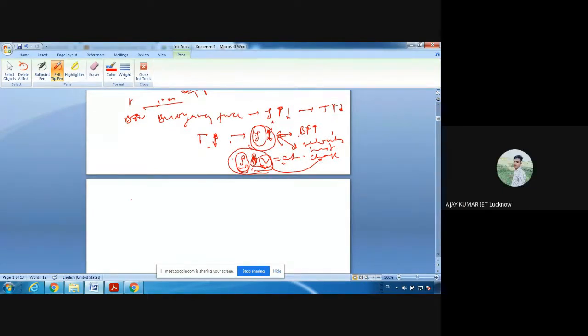Yes, sir. See, if temperature varies then there will be variation in density, and with variation in density, the buoyancy force is one impact of the density variation. Second, if there is variation in density, then to conserve the mass flow rate, velocity must change. So there would be variation in the velocity as well due to density change, or due to temperature change, because the density change will happen due to temperature change. So this cause and effect relationship you must understand.